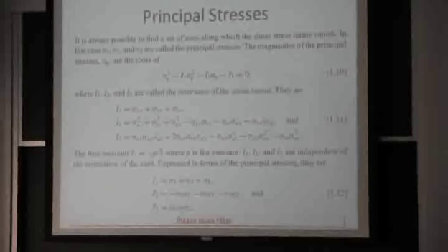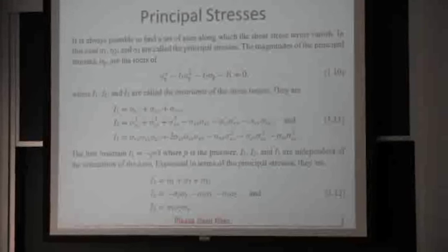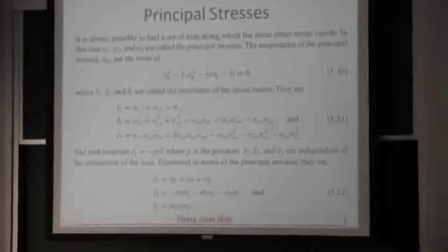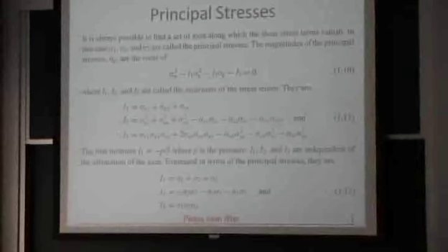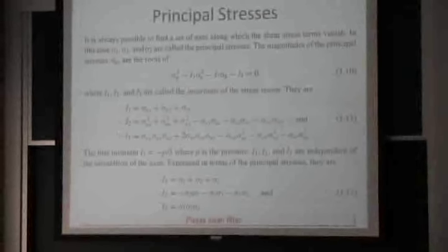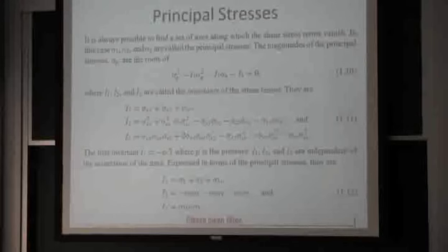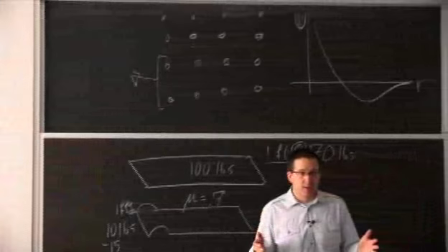So if you're going through a rolling operation or any forming operation, there'll be some restraints on the material you're working with, and that stress state will determine whether you'll be able to make it to shape all at once, or whether you have to do it in multiple steps.